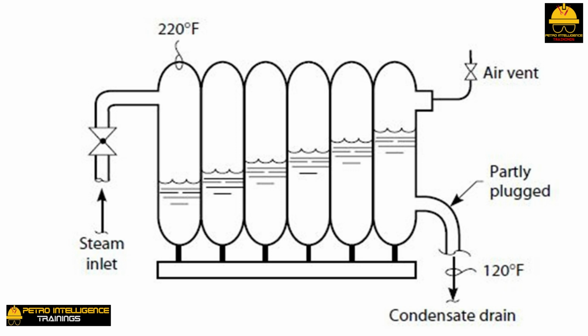Calcium carbonate is a typical water hardness deposit. Anyone who has lived in an apartment house in colder areas will have had to occasionally bang on the radiator to increase heat flow. Banging on the radiator often breaks loose the carbonate deposits in the condensate drain line. The steam condensate, which has backed up in the radiator, now empties. This exposes more of the interior surface area of the radiator to the condensing steam.